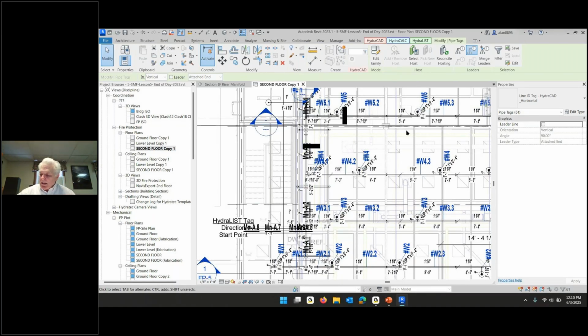And under pipe I've got center to center or cut or dynamic, but under that is the stock listing tags. Okay. And then when you pick stock listing tags, you say, do you want to tag at the beginning of each run or in the middle of each run or at the end of each run? And I picked middle. Okay.